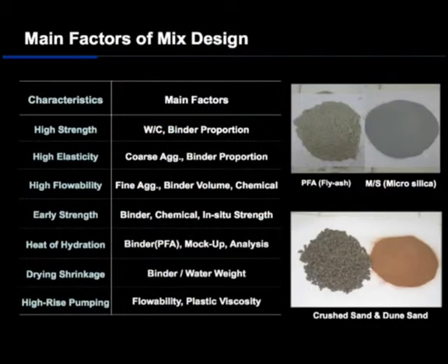To meet all the characteristics of the concrete, we have to consider all those points: strength, elasticity, high flowability, early strength, heat of hydration, drying shrinkage, and high-rise pumping. And we have used fly ash, microsilica, and crushed sand. This, especially dune sand, provides good flowability.